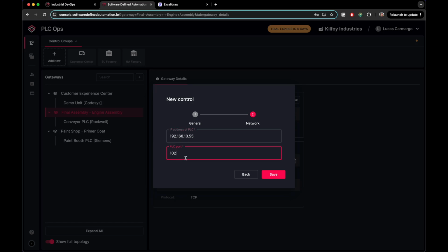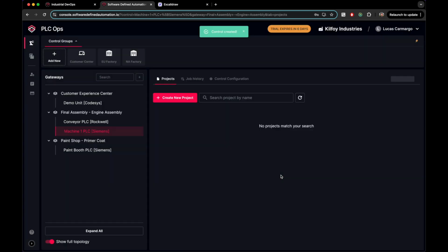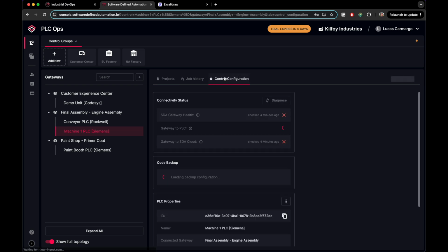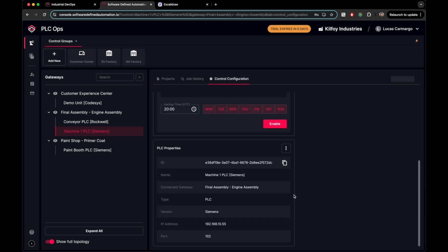Each vendor will likely have a standardized application port for the IDE. Like in this case for Siemens, the port is usually 102. However, your project configuration might change this, so be attentive.